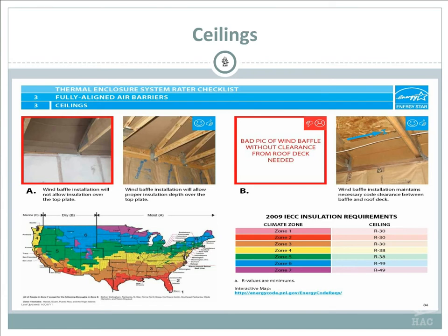So again, depending on how much insulation you need, in our area we're not trying to keep the heat in, we're trying to keep the heat out. So we do a lot of things differently. We insulate the ceilings, we insulate the decking. We put foam board on top of the decking and below the decking, so all that heat is reflected back out. We use white shingles, those types of things.